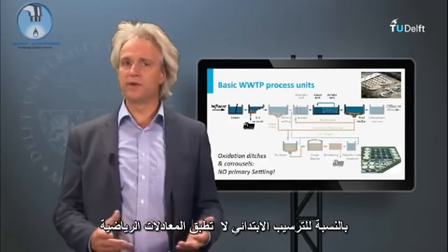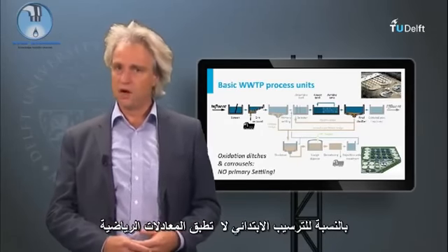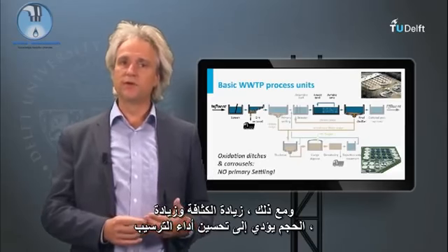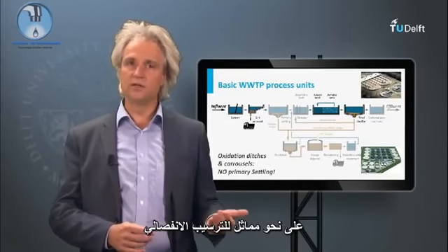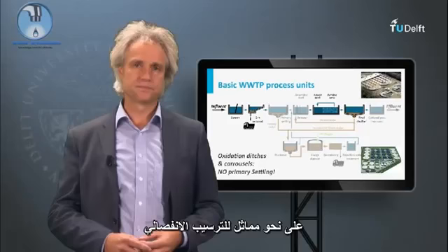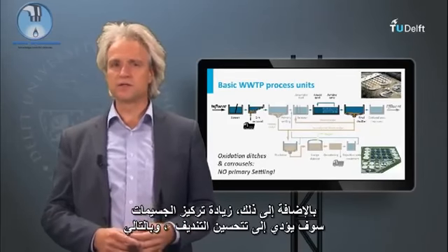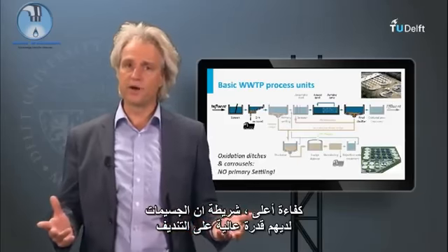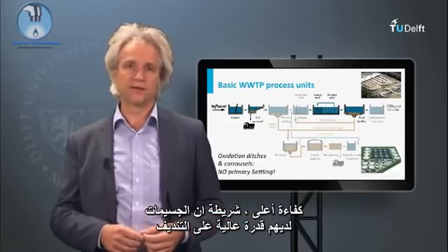For primary settling, no mathematical formulas apply. However, increasing density and increasing size will lead to improved settling performance, similarly to discrete settling. In addition, increased particle concentration will lead to enhanced flocculation and thus higher efficiency, provided the particles have a high ability to flocculate.